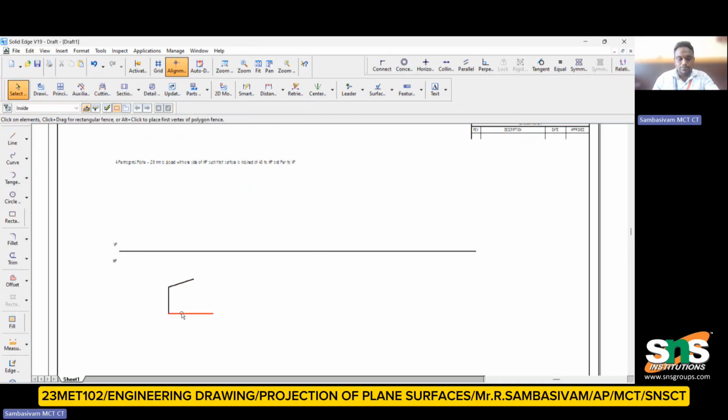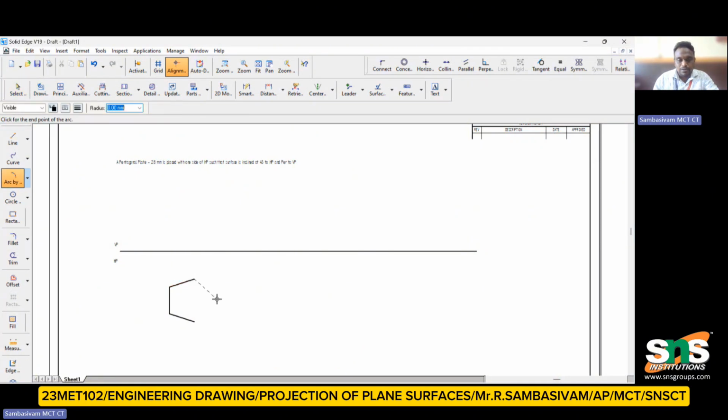Similarly, from this point, I have to make a 28 mm line at minus 18 degrees, so another side comes. Similarly, I have to draw an arc by center point from this point, with radius 28.